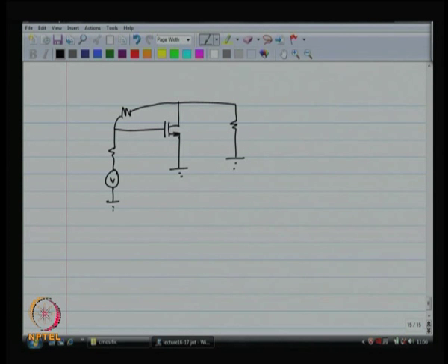All right. This might not be sufficient, you might need something like this as well. So, this is called shunt series feedback. So, you have put R in series and R in shunt to your amplifier. So, the shunt series amplifier also can improve speed dramatically by playing with the gain, right.